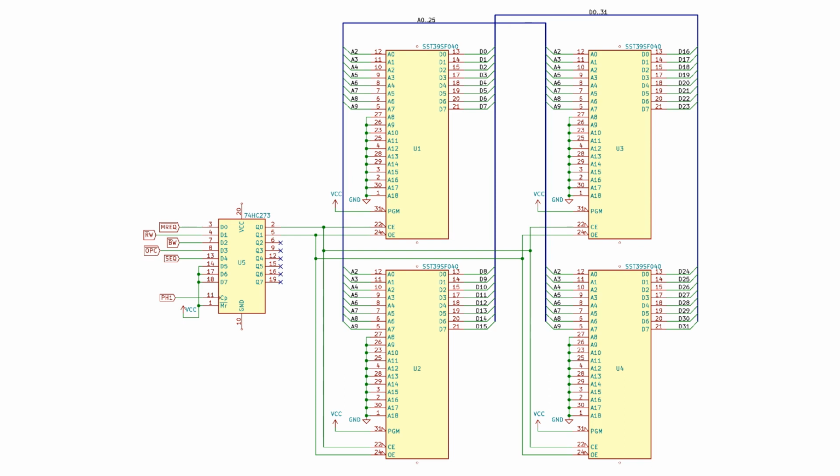And then I've used a combined 8-way D flip-flop here because there's a whole bunch of signals that we want to latch on the rising edge of phase 1. So I might as well put them all through one IC here. And this is a 74HC273. In particular, the memory request and the read-write line are the most interesting ones at the moment for the ROM-based system. These other ones I've put on here I think are going to be useful for when we add RAM. I don't know, some of them aren't useful at all really, but I thought I might as well put a few more on.